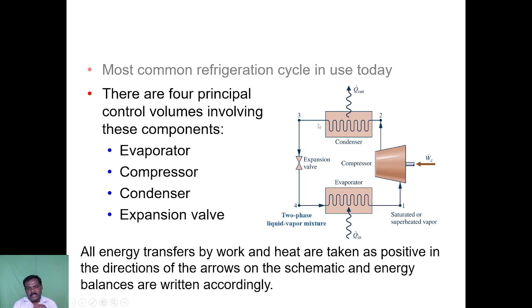So this is the principle. We have to find out the working principle of this vapor compression refrigerator. As a mechanical engineer, you should know what thermodynamic processes are carried out in each and every component. So first I can start from the compressor. The input to the compressor is from the evaporator, so the evaporator output enters the compressor.